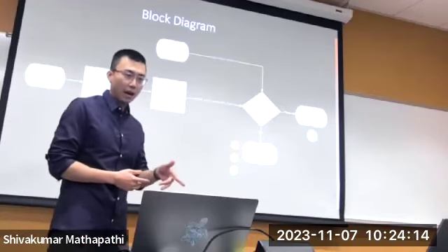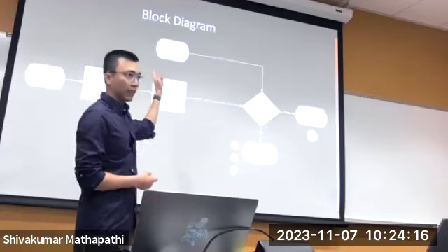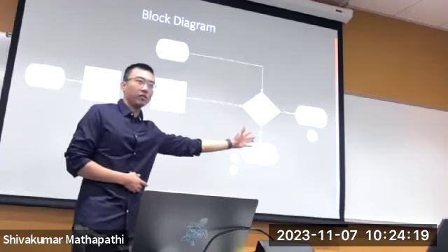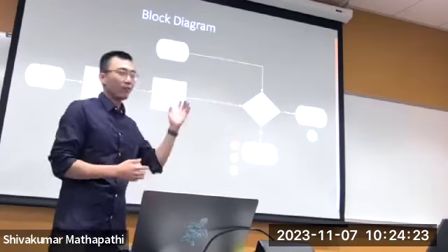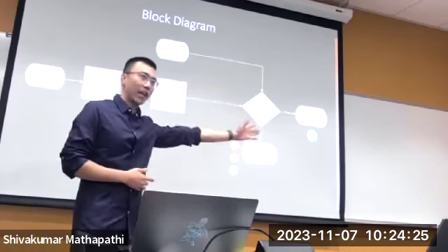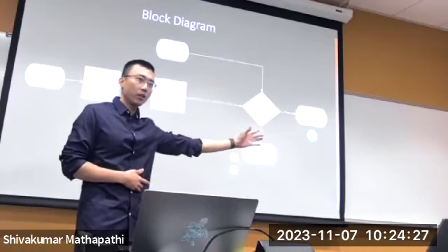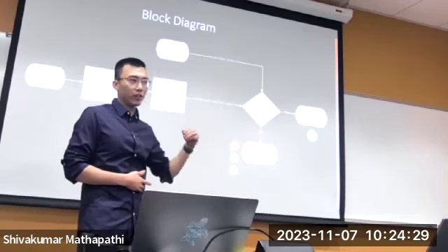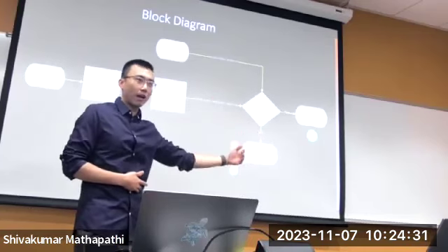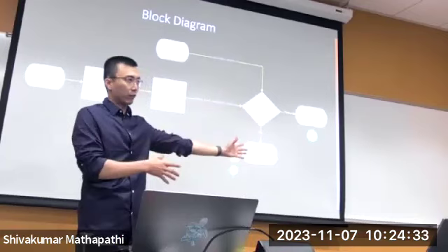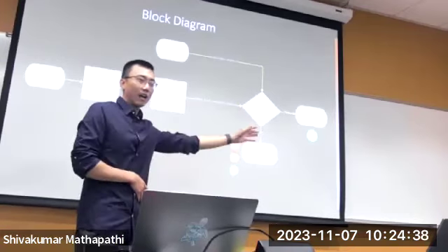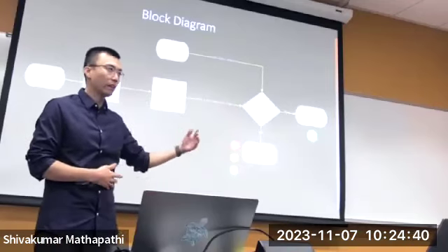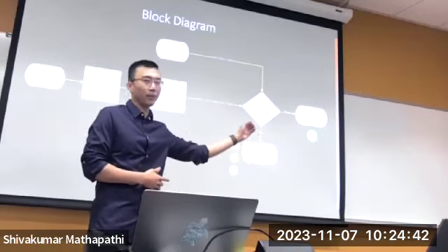At the same time, we use the ultrasonic sensor for another direction, because we only have one camera available. We use this ultrasonic sensor to get the distance for the other direction. If the distance is larger than a certain value, we can say that direction is clear, no pedestrian is walking by. If it's less than a certain value, we say that direction is busy, somebody is there.